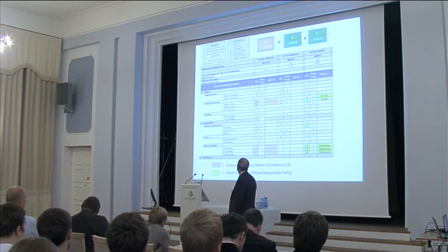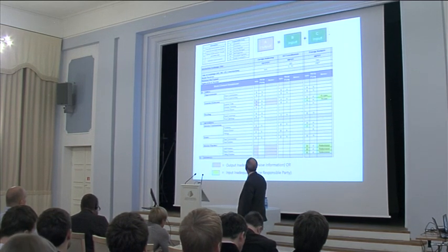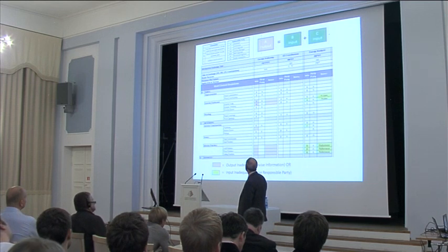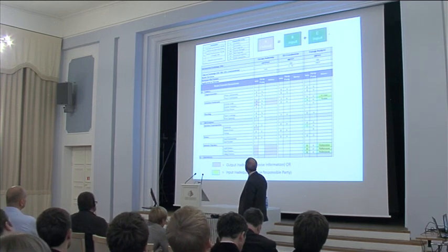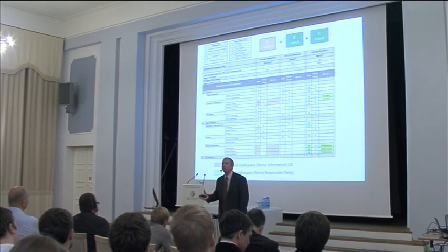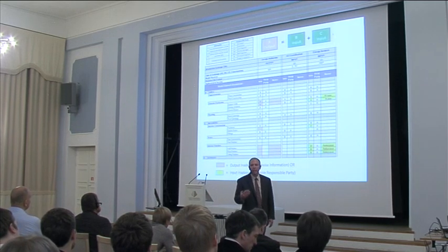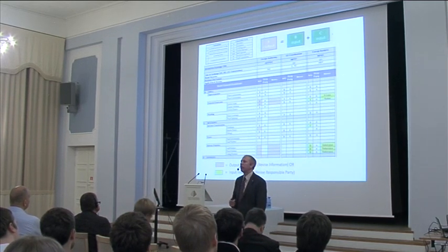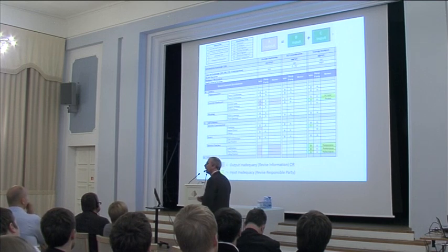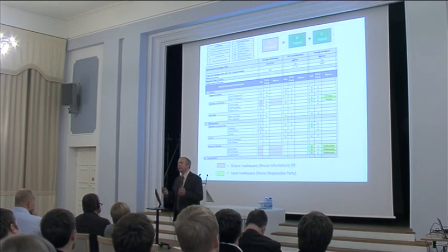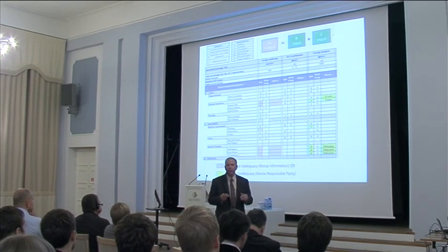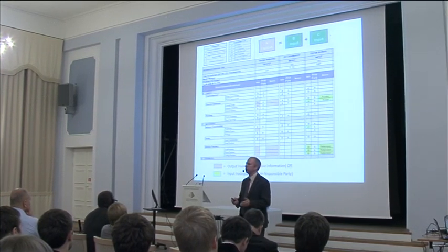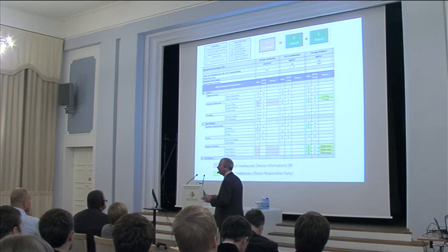And then as you go across the side, you're looking at different BIM uses. So this would be design authoring. So what do we want in that information handoff? So do we want the floor construction? And if we do, how detailed should that floor construction be? And who should do it? And so this is just a way to be able to go through for each of those information exchanges and really start the conversation. And that's a key point here.